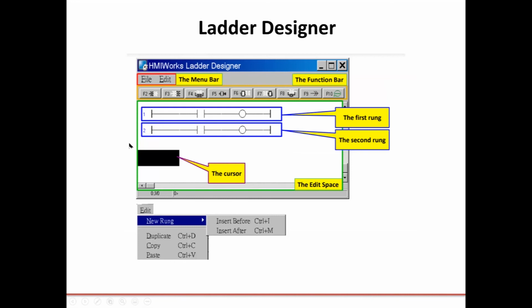Okay, so that is all I want to say about designing the GUI. Let's talk a little bit about Ladder Designer. Ladder logic is a programming language that is represented by graphical diagrams based on the schematics of relay logic hardware. So conditions on the left lead to outputs on the right, and logic functions are implemented by developing a ladder diagram. The reason it's called a ladder is because it looks like a ladder, with the functions going into the horizontal rungs.